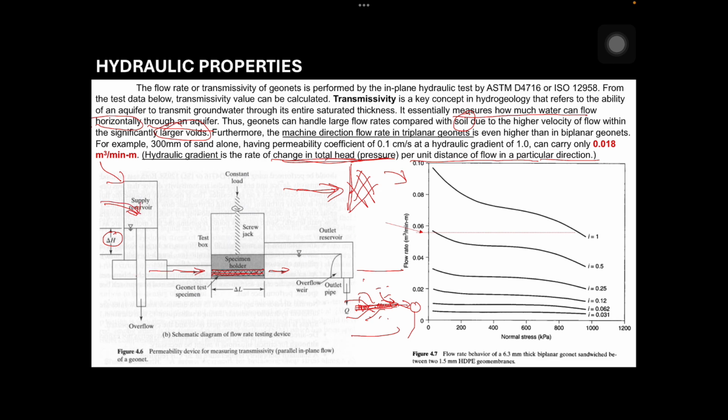And then, our water will flow horizontally. It goes to our main test structure here. So, your geonet and its corresponding covering are here. Whatever is designed, the chosen coverings, whether geomembrane or geotextile, are placed here. And then there are plates there, with rubber or foam to prevent leakage upward, so that it does not leak.